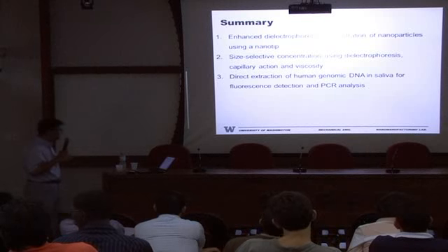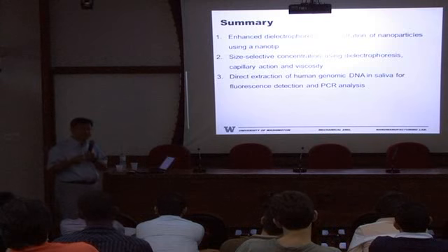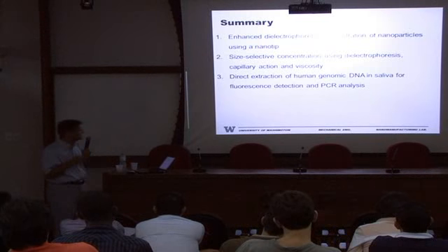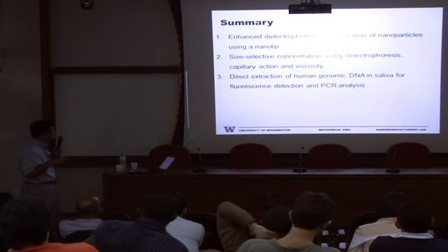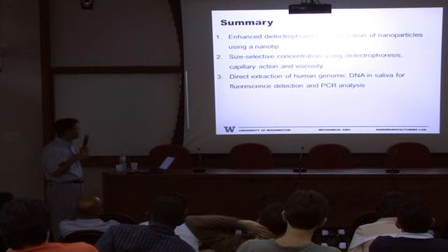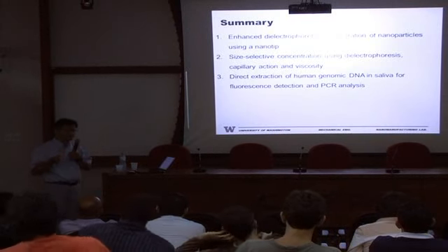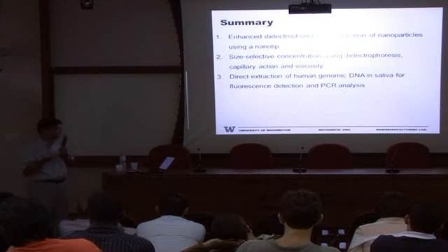So in summary, we studied the dielectrophoretic concentration using a nanotip in experiment and then numerical simulation, and they agreed quite well. Through the size selective concentration using dielectrophoresis and capillary action induced force and viscosity, we could directly concentrate DNA from a sample mixture.